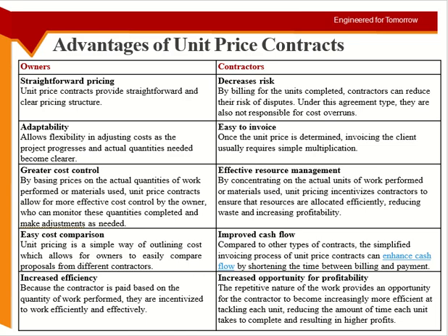Okay, so if excavation required more effort, you must have given a higher unit price for it. Okay, if paint requires less effort, the unit price would be less. So the work which requires more effort has a higher unit price, and you get the money when that work is done. Okay, it's not calculated from the whole project. It's case by case basis, work by work basis.